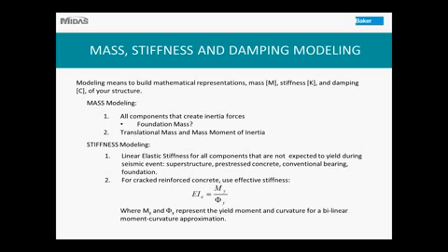there will be relative displacements, therefore there will be relative accelerations from the foundation mass to the ground. Therefore, there will be inertial forces associated with the foundation mass. Therefore, you need to model those foundation masses.